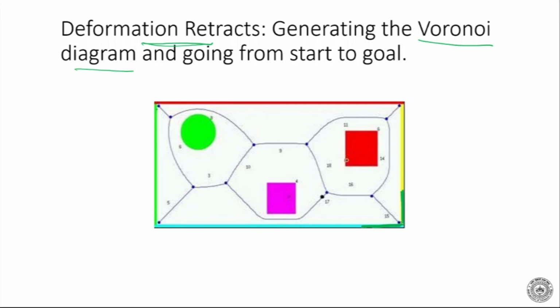So we have one side here, another side here. I start from here. Points which are equidistant to both these sides form one line. Similarly, it's one line there, one line here, one line here. These points are all equidistant to two sides. Now there's an obstacle here. If you imagine this obstacle expanding, and this is also expanding, where will they meet? They will meet here. So this is my network of paths now, which are equidistant from the obstacles and the sides.